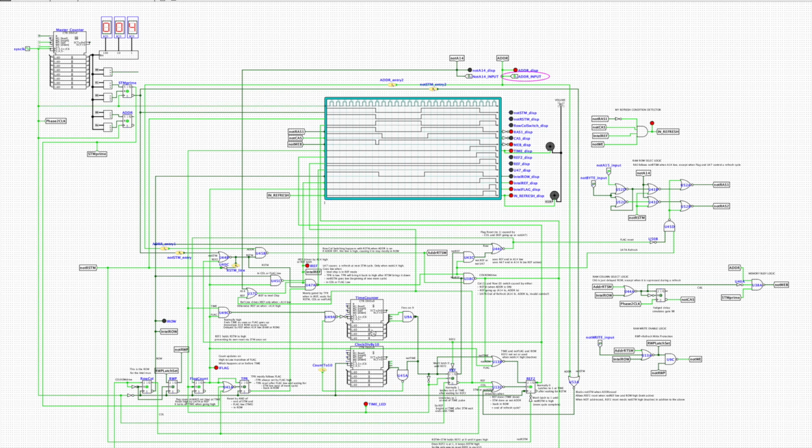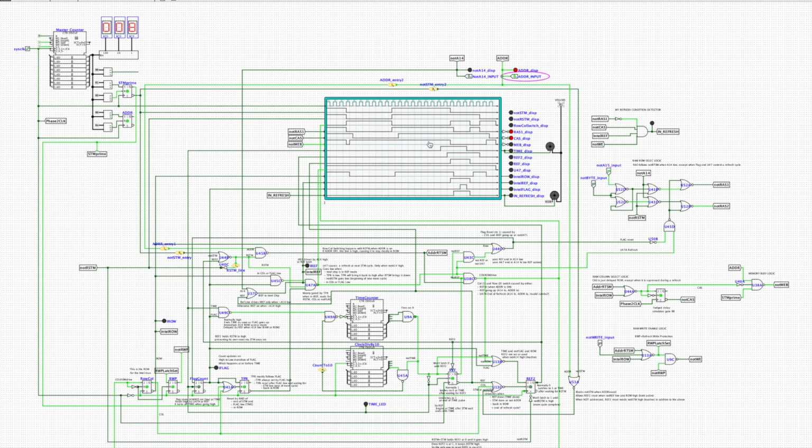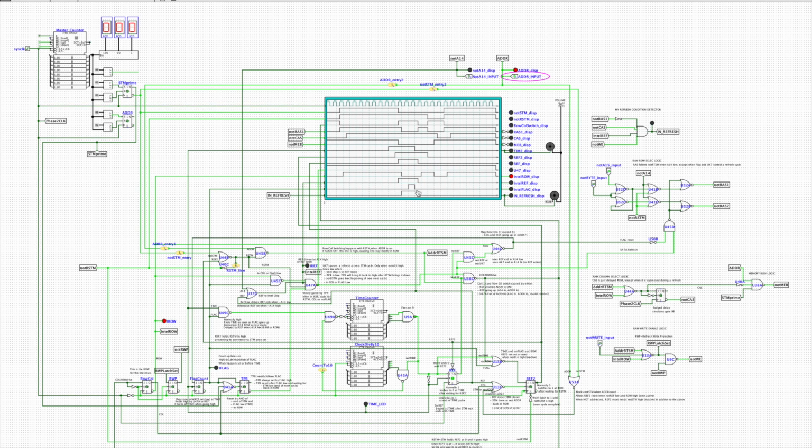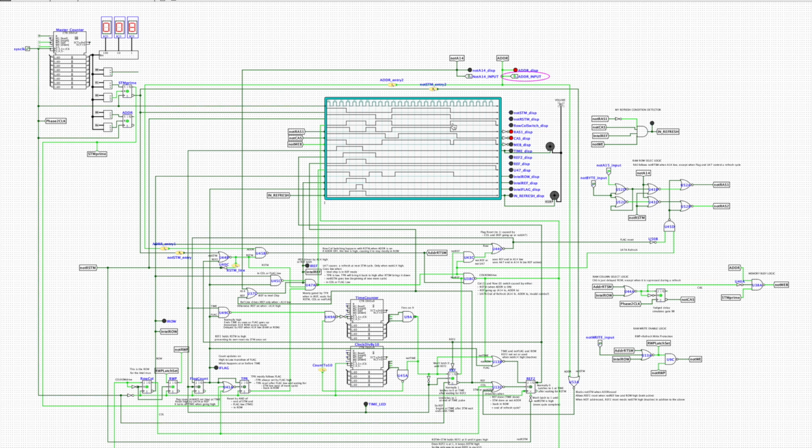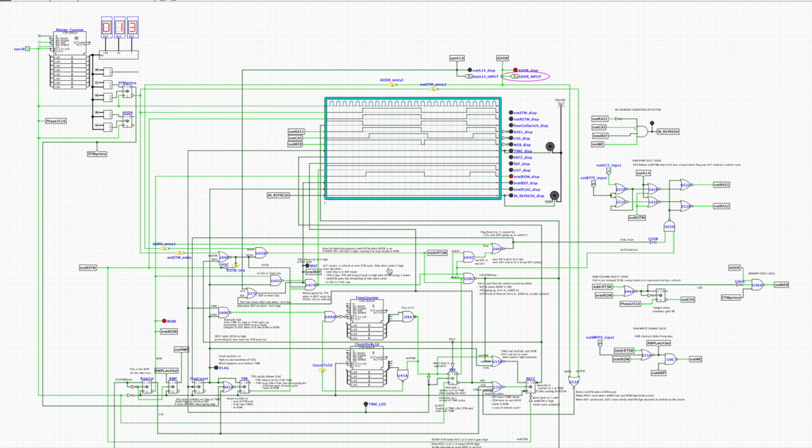Here we go. And so the low beep was the time to start the refresh, and the high beep is when the refresh actually happens. And depending on the timing of the memory, it can happen right after the counter has timed out, or it can take a while to align on the memory cycle, so the refresh doesn't trump on a current cycle by the processor.